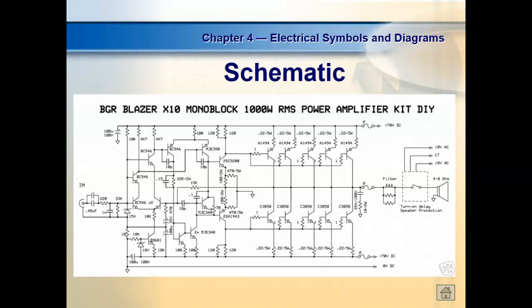And this is just one channel too, guys. This is so people understand why we need plus and minus power supplies. Well, this guy works off of AC. These guys work off of DC. So notice down here we have a minus 70 volts DC. Up there we have a plus 74 volts DC. These guys turn on right here to generate the bottom part of the alternation or the sound wave, these turn off, and then those conduct the top. So this is why we need plus and minus power. So inside your radio, somehow they're taking 12 volts DC and converting it into a plus and minus DC. But they're doing it electronically, right?